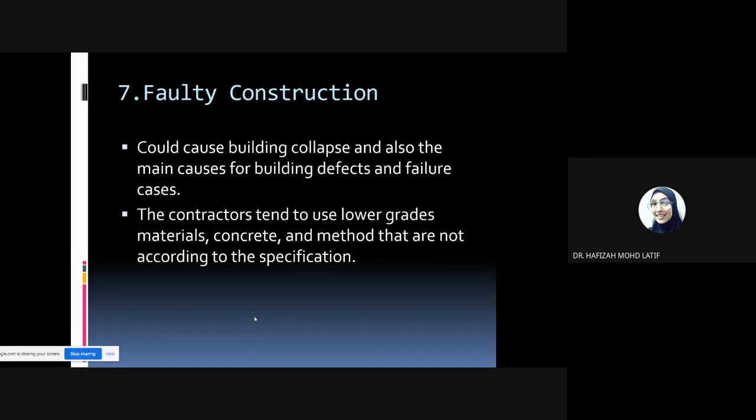He wanted to save a few pounds, and he eliminated that screed, and he just laid the, what do you call this? Tiles. So they didn't have the screed, but they just put the tiles on the concrete. And we know concrete shrinks and expands over the years. And if you don't have mortar or screeding on top, it will affect the tiles.